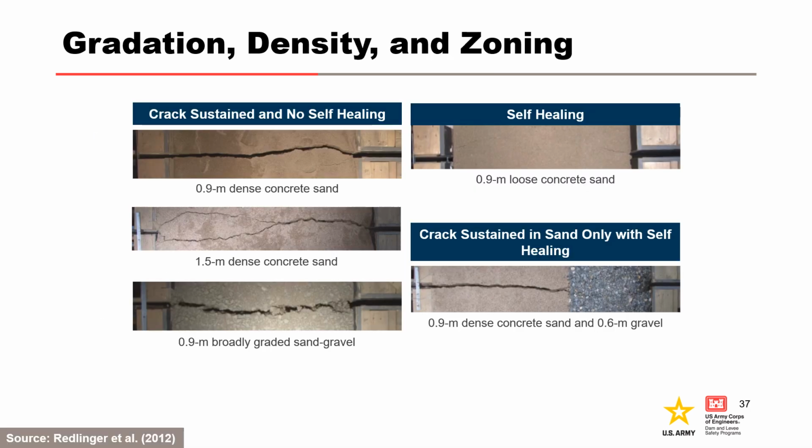Reclamation and USACE tested commonly used filter materials, moist concrete sand with less than 5% non-plastic fines, in single-stage and two-stage vertical chimney filter configurations. The densities at which the tested filter sands flowed freely and self-healed were very low, much lower than anticipated. In most, if not all cases, it would be difficult to consistently achieve this low of densities in the field, and if achieved, it may be impractical to ensure they remain at such low target density due to construction of and associated loading from adjacent and overlying fill.